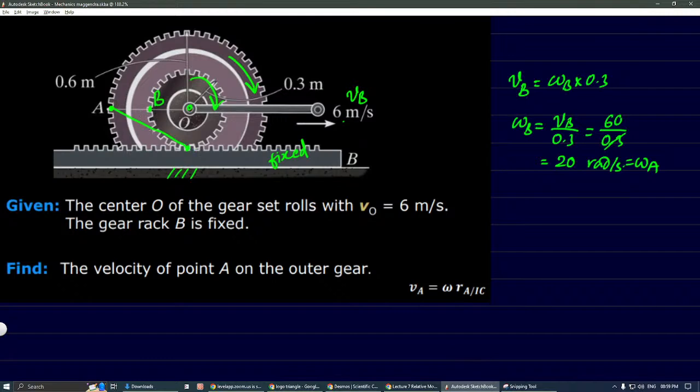So that we need to use. If A is joined here, that will give the instantaneous center. This is the instantaneous center. So that instantaneous center we should use. Here this omega will be the same. Let's say velocity of A is in this direction, velocity of B is in this direction, right? So omega will be velocity of A divided by the radial distance.